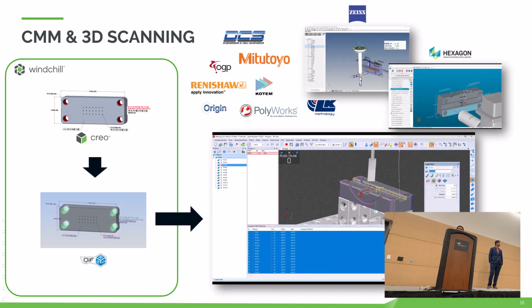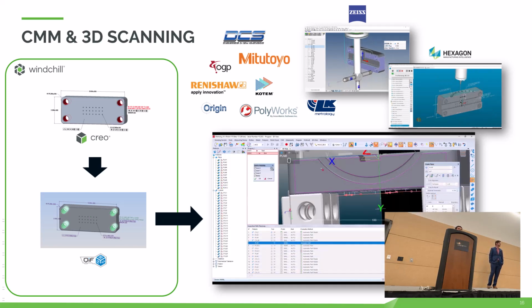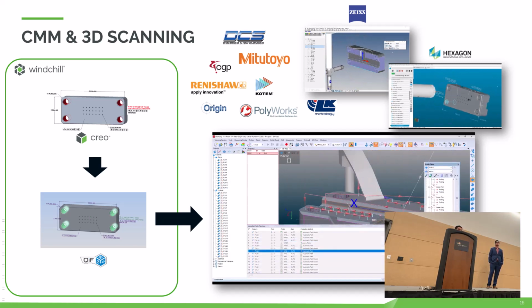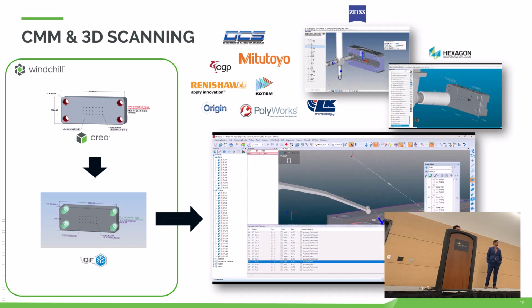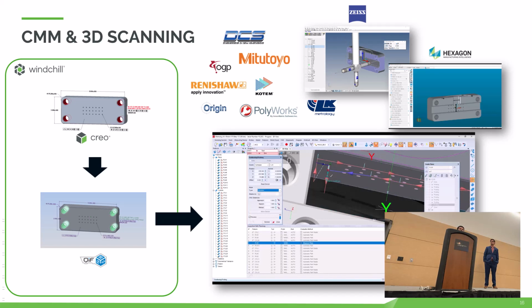That means you're automating a lot of the process, which is typically done manually. A CMM software will open this file, recognize all the features, and understand that hole 1.1 should be a certain diameter with a positional tolerance. So you're really automating this process, and no longer are you having issues of somebody typing something differently.